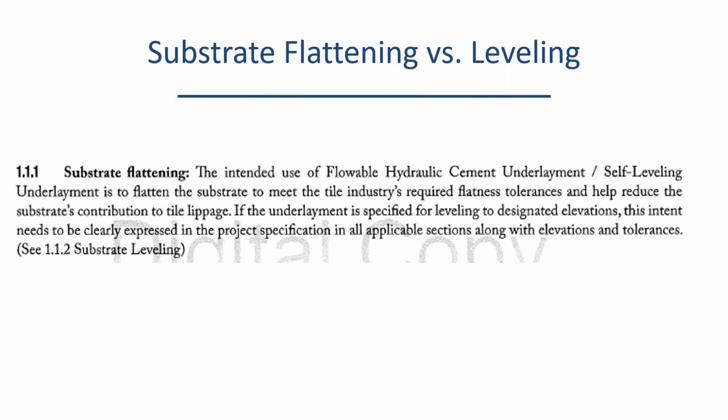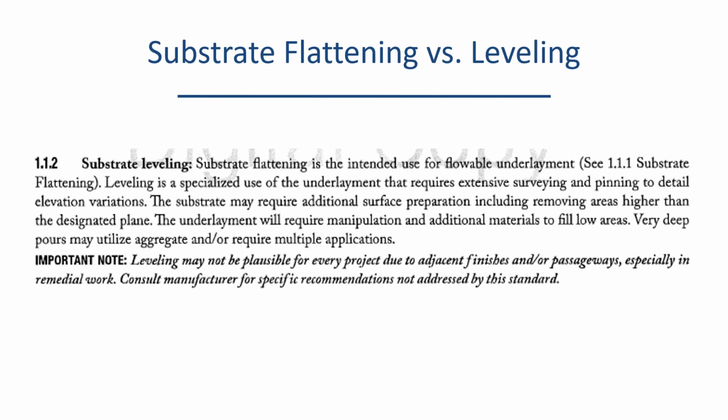If underlayment is specified for leveling to designated elevations, this intent needs to clearly be expressed in the project specification and in all applicable sections along for elevations and tolerances. In other words, you cannot assume that because the self-leveler is specified, it is intended to be perfectly level. That is a different animal.